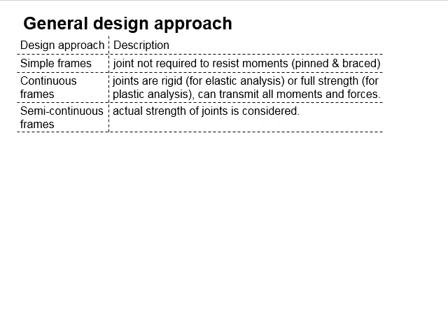The design approach is founded on three methods, which are the simple frame, continuous frame, and semi-continuous frames. While designing for simple frames, the joints are not required to resist moment. That means the connections are considered pinned and the structures need to be braced.